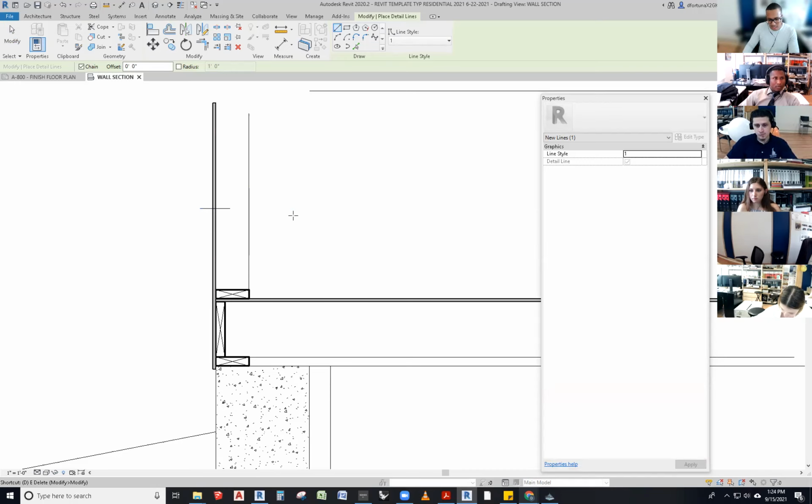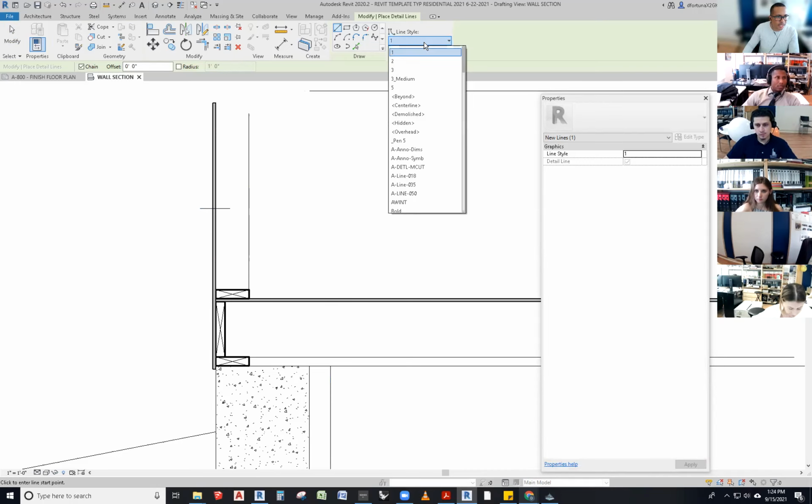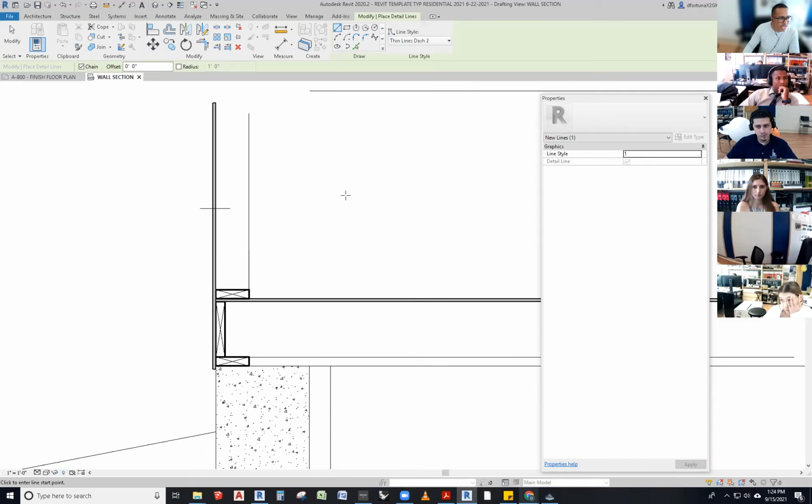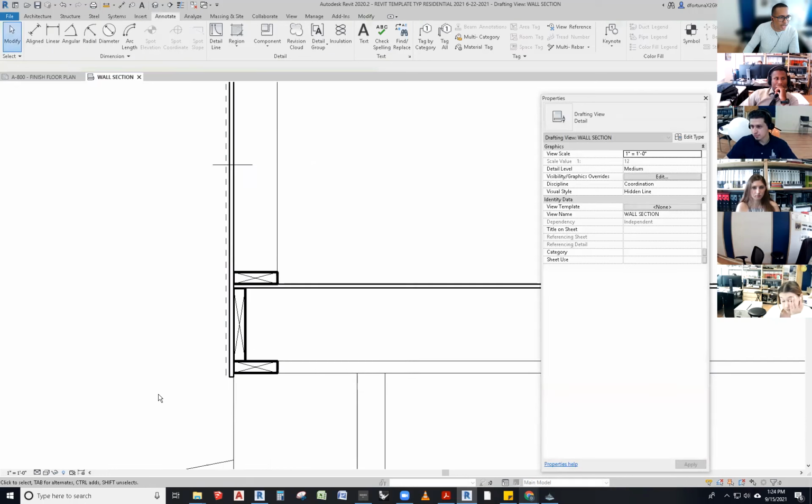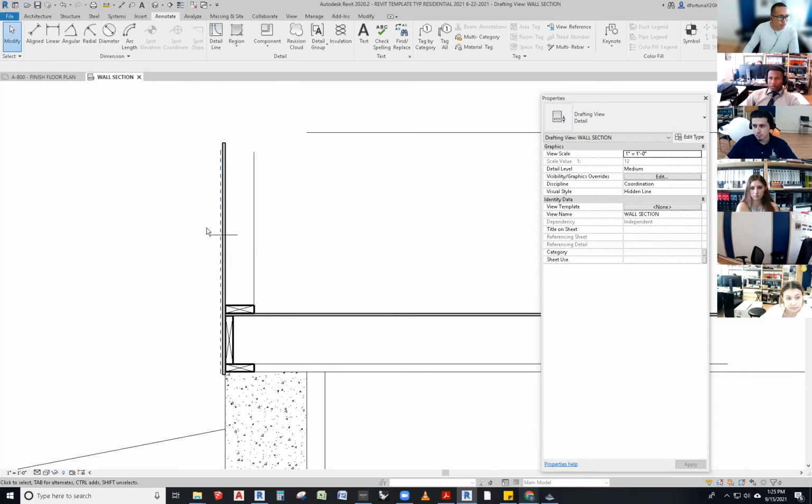Typically, like I said, if they don't have a zip system, which is again something very detailed, I don't have to go into it right now, you put some plastic. You've probably seen some buildings that have some plastic. That's for air and vapor barrier. We represent it with the dash line. Then what goes on top of that? What you guys see, the finish. The finish is a thermal protection and water protection. The other one is the heat protection, and the finish is the actual thing that will protect us from the weather.